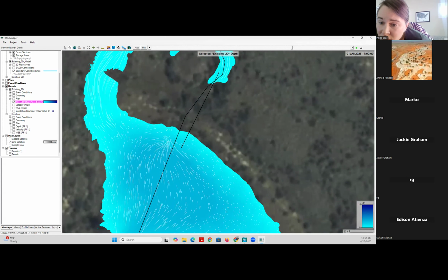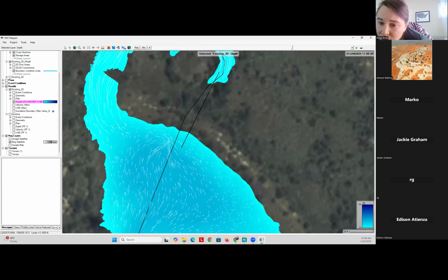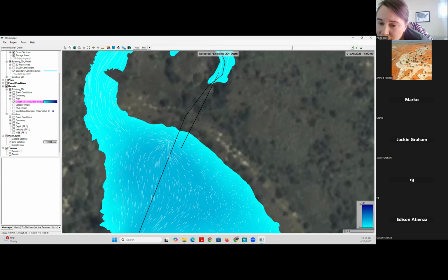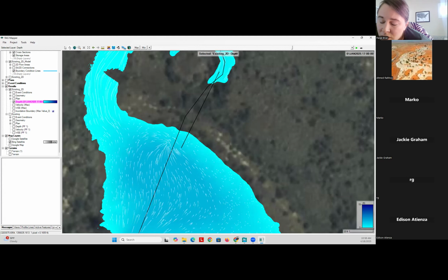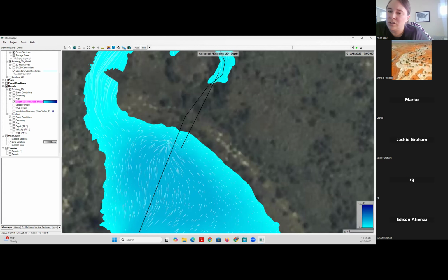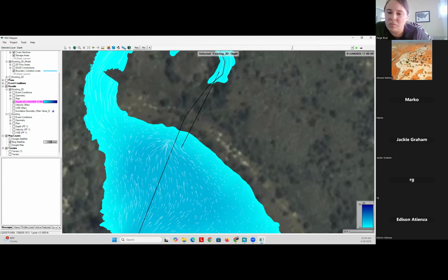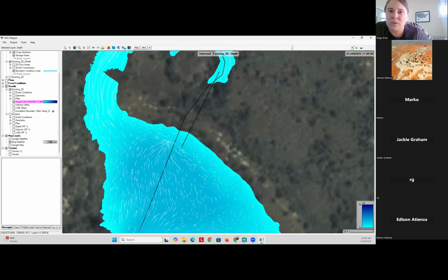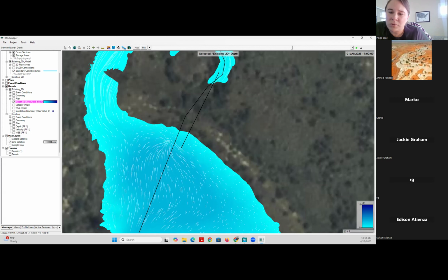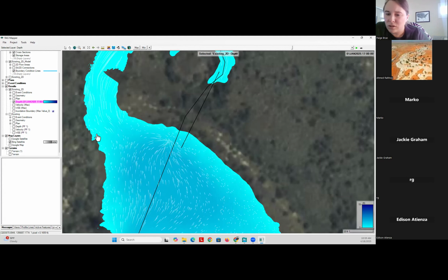How do we take into account groundwater flow? Yeah, you can. They have infiltration. There's infiltration capabilities, Michael, but there's not really a way to model groundwater and surface water together. But there are infiltration capabilities in HEC-RAS.